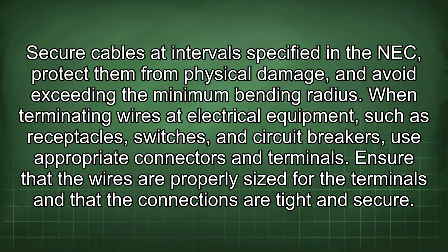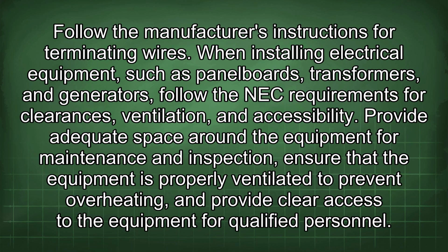When terminating wires at electrical equipment, such as receptacles, switches, and circuit breakers, use appropriate connectors and terminals. Ensure that the wires are properly sized for the terminals and that the connections are tight and secure. Follow the manufacturer's instructions for terminating wires.